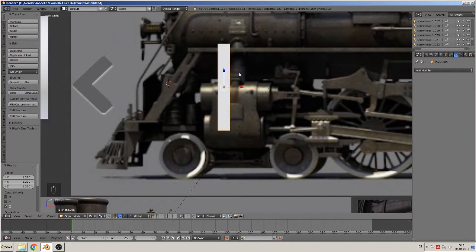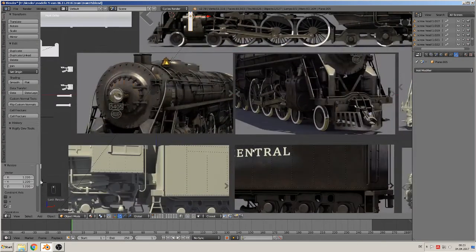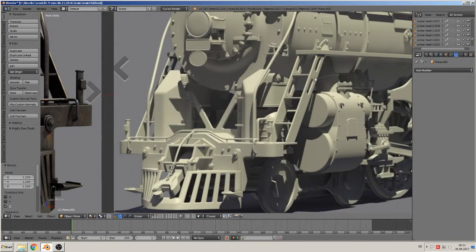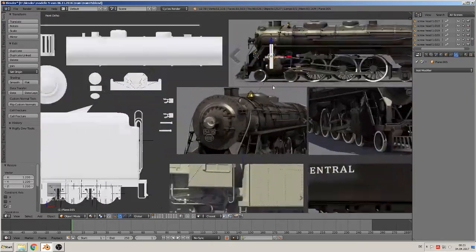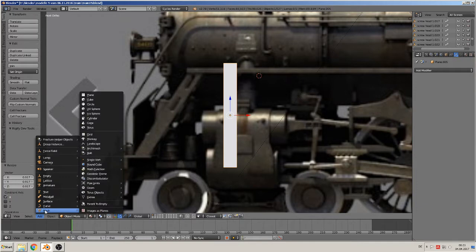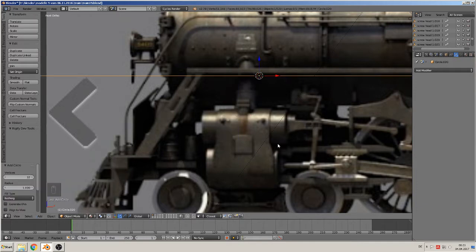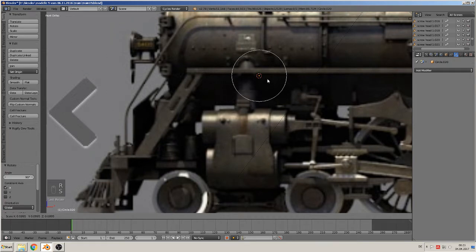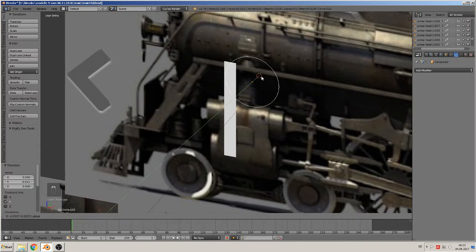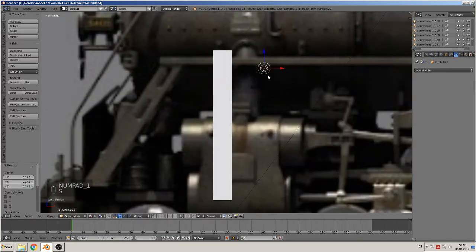And you see there are holes in. We see it better on the other side here. Here you see these holes that we must cut in. So that needs 2 of them. So we scale X a little bit more. Then we add mesh circle, rotate X 90, scale down, bring that in front and the circle also. Now we scale to the size for the hole that we want to have. I think that is good.